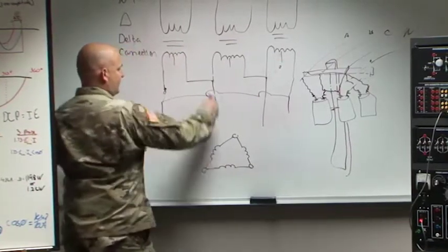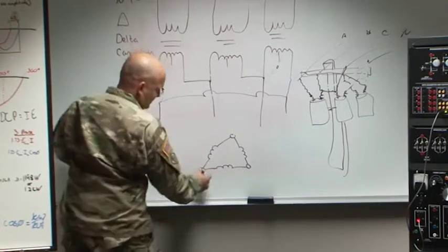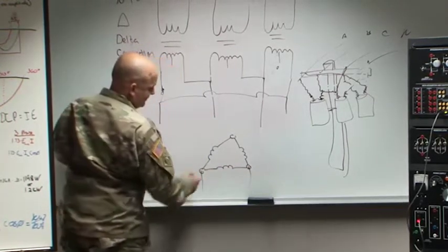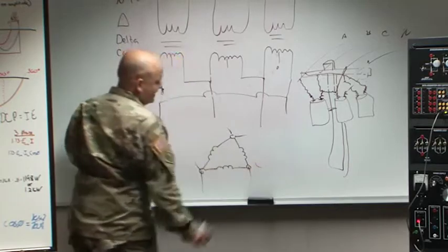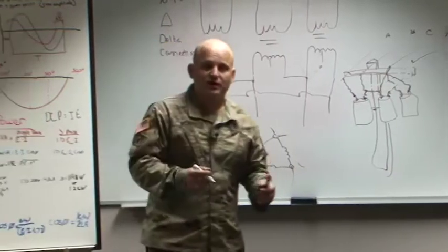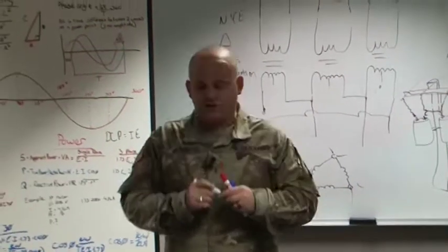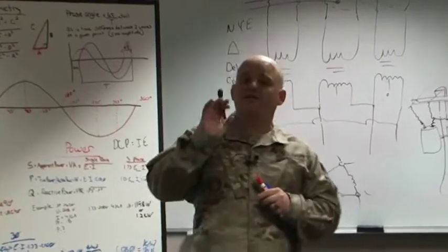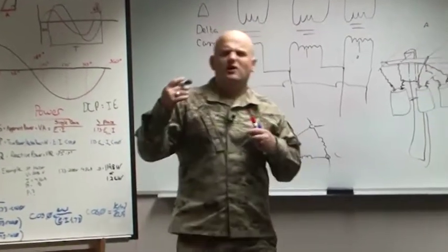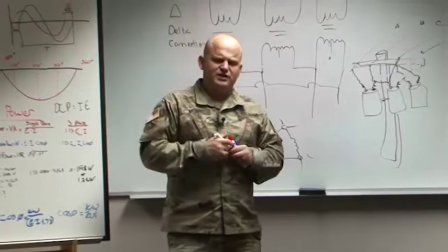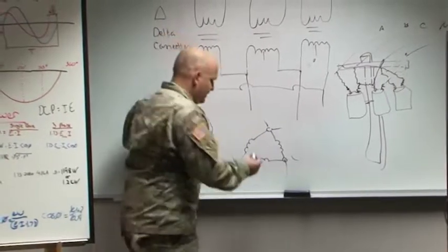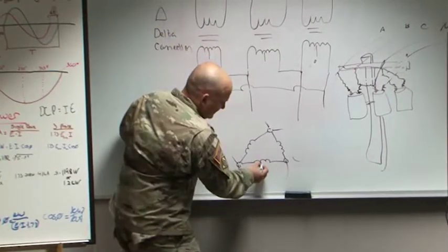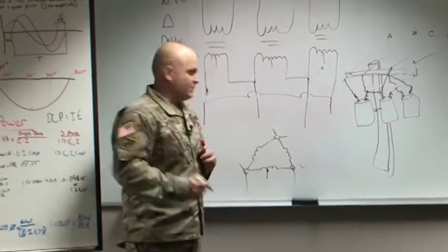And now the loads coming off of it would be, well, where am I tapping my load off of? Am I tapping a potential difference from here to there, there to there, there to there? It doesn't matter because it's the same between all of them. When we get into configurations in which you would want to get some type of varying voltage off of a delta connection, now let's go back to that auto transformer concept, or maybe the distribution transformer concept, and say, well, what if I tapped off one little spot over here, this little short nugget over there, and reference it from one of these?